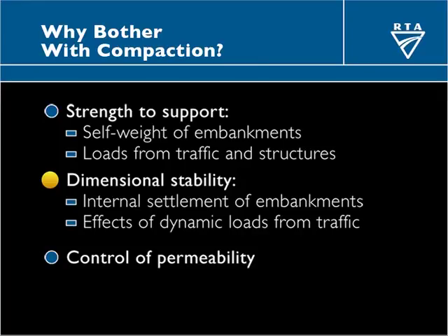We're also looking for what I've called dimensional stability. That relates to two things. Firstly, the internal settlement of embankments under their own weight, as that weight under the force of gravity reduces the void content. And secondly, we're looking at the effects of dynamic loads from traffic, both the loading and unloading cycle from passing vehicles, and also the thumps and bumps that you inevitably get from passing traffic on an uneven surface.